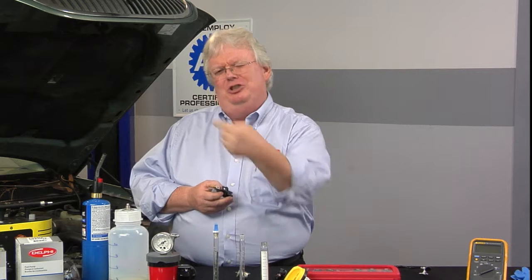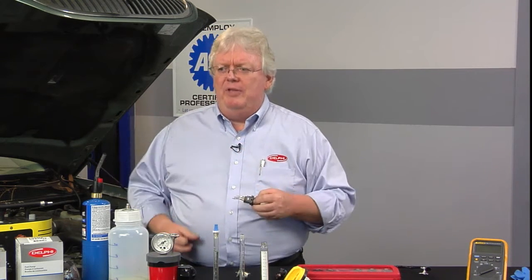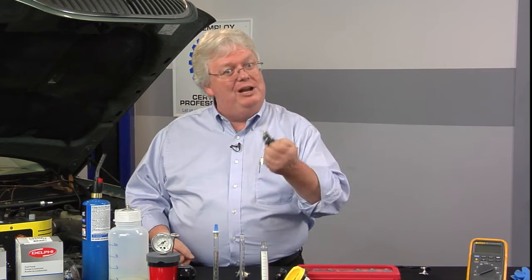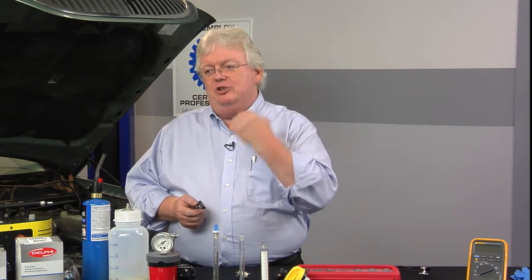They should code. Obviously the propane and the vacuum leaks will have some success, as you saw on the Explorer. Limited success on making that wideband sensor get excited one way or the other, but it does happen. So that's one other thing you can do, is just good old-fashioned drive them rich and drive them lean and see if the trims change, see if that sensor's changing its value. Obviously you can look at the post-cat sensor as well.